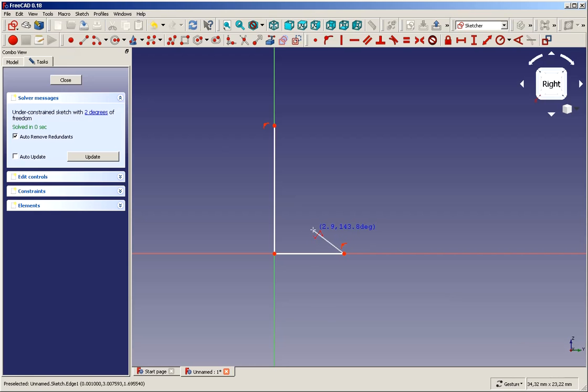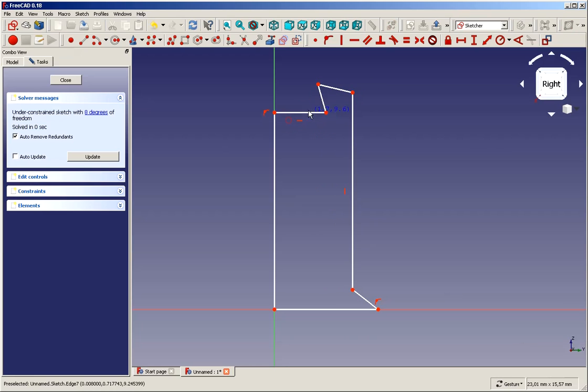So let's go over then to the main part of the knob. As you can see, I don't really care about the values. I just sketch how it will probably look afterwards. Using the right mouse key I end this mode, and the first thing that you should always do is check whether your lines are really connected, which in this case is okay.